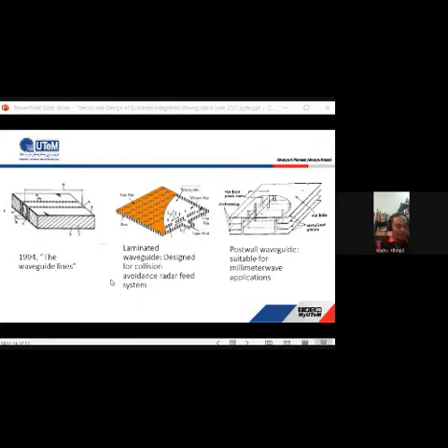It acts as a side wall, and it can also act as a planar structure. If you fill the holes in the waveguide with dielectric, it becomes planar. People started using multi-layer configurations, laminated waveguide, parallel plate waveguide. So it is a good candidate for high frequency applications.